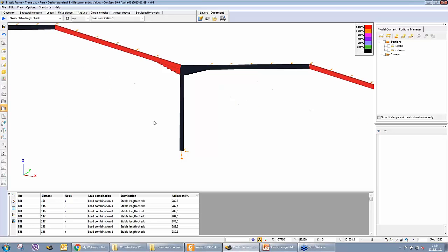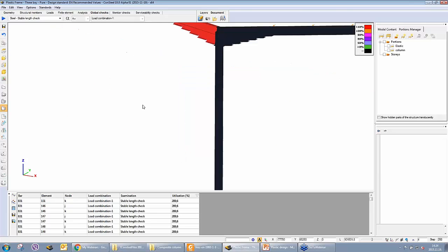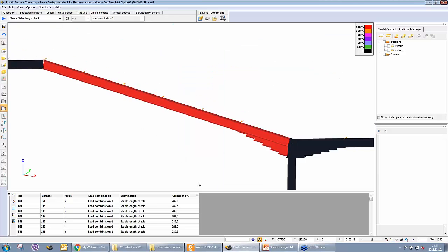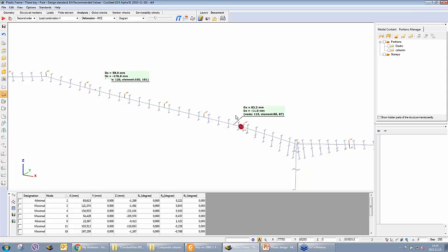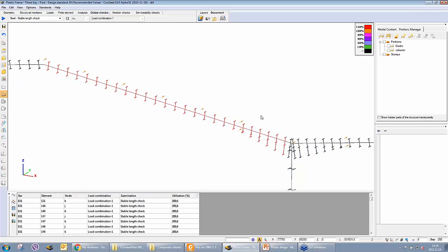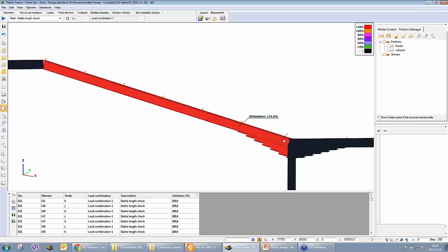So here we have, let me start with this beam. Here we have the plastic hinge, as we remember. So we have to go in that way, and the column is the first rotational restraint, and inside this length we have no further lateral restraint at the top flange.